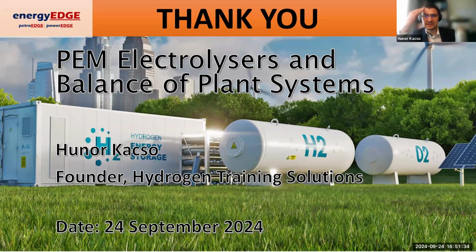PEM itself stands for proton exchange membrane, but it also stands for something else. PEM also stands for polymer electrolyte membrane, which means that the membrane itself is the electrolyte. So we don't actually need to flush any electrolyte on the surface of the membrane. All we have to flush is very pure water. Therefore, we don't need an electrolyte in PEM.